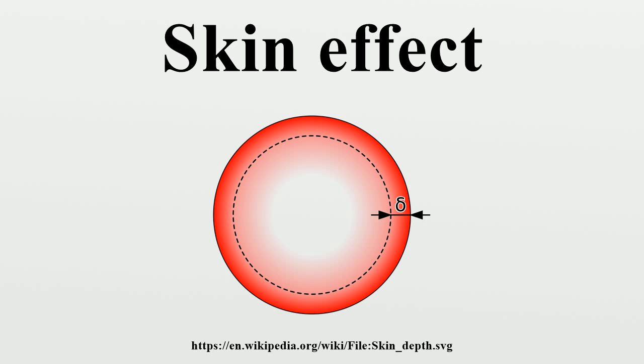Tubular conductors are typical in electric power switchyards where the distance between supporting insulators may be several meters. Long spans generally exhibit physical sag, but this does not affect electrical performance. To avoid losses, the conductivity of the tube material must be high.